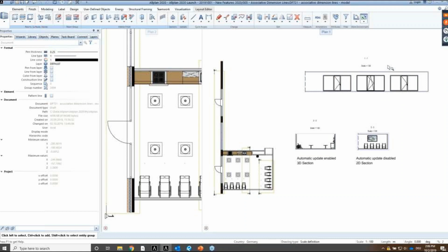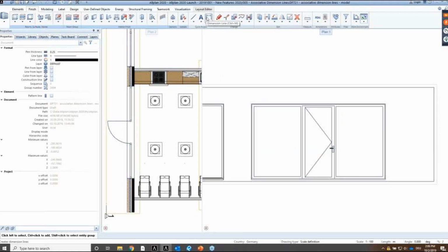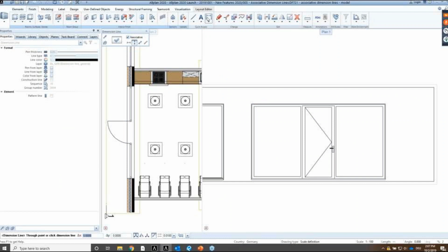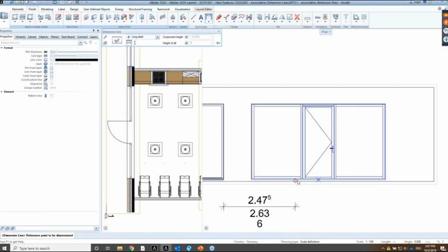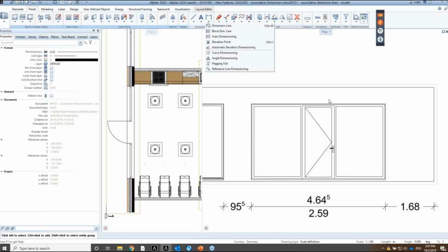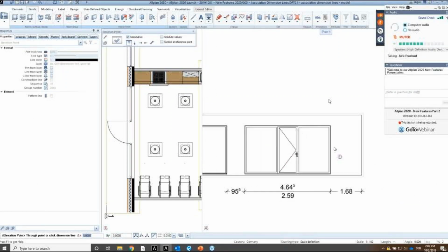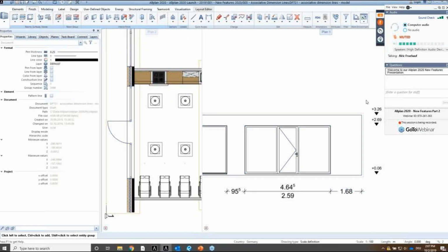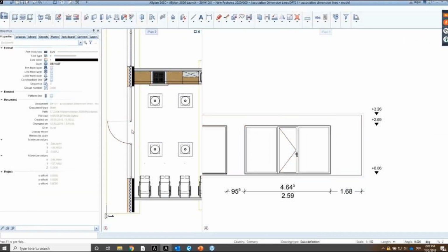This means that for you as user, it's no big deal. When you manually make a dimension line, even for 2D, you just have this small tick, associative. What this associative does is it will track vertices. So points of variation on an item, which can be 2D, 3D, doesn't matter, are now followed. So there's a direct link with the vertex that generates that object, and the value of it. So now you see that target-like sign. It means that the offset is really demanding now because it will follow items.